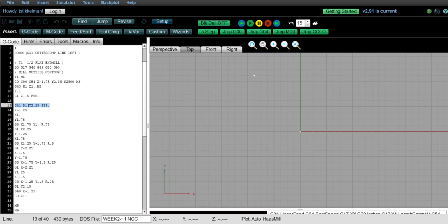Okay, so that's what cutter comp does. If it's a -5 in that column and brings that in, when it sees that D1, then it thinks that the end mill is .495. So it takes 2.5 thousandths per side off for an overall dimension of -5 thousandths on that 4-inch dimension. Okay, I hope that makes sense. So let's complete that move.